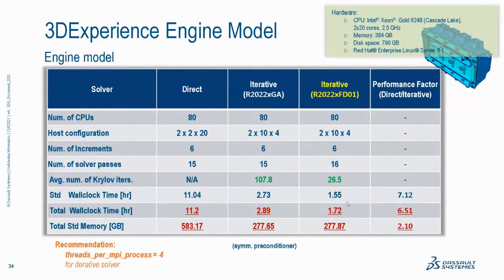Here we're looking at standard wall clock time. If we actually looked at just the solver performance, you'd see about a 4x increase in the performance of just the solver. Here we're looking at total standard wall clock time, which includes element calculations and so forth.